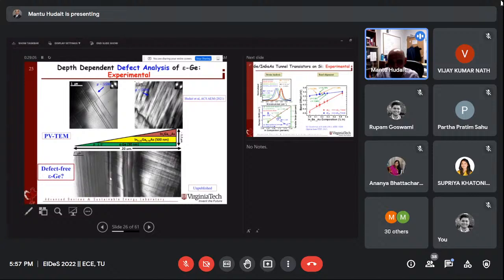And you see the red dotted line, those are the different images he took and put together for the TEM. This we didn't publish yet, we're going to send that. It is telling us that for the strained germanium, the 30 nanometer, as you see on the left-hand side, it is very hard to see misfit dislocations. Does it mean that it is zero defect?